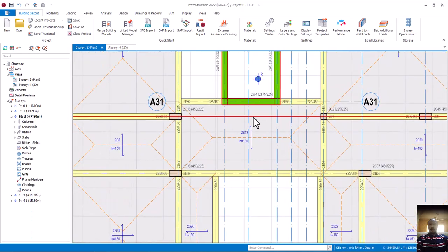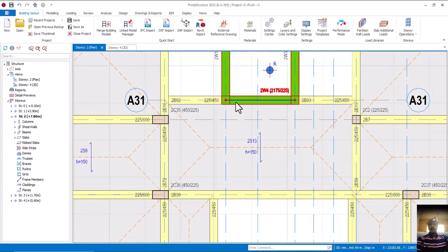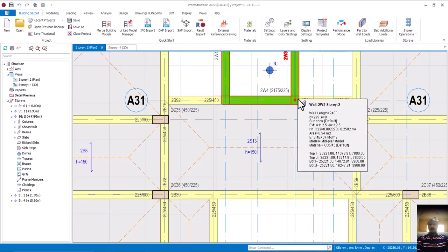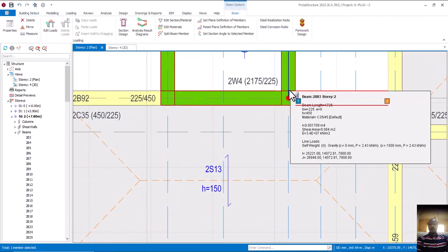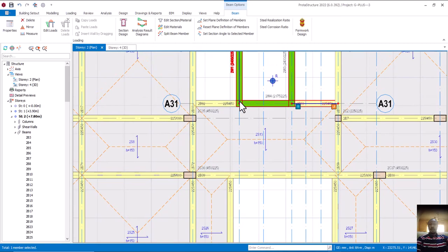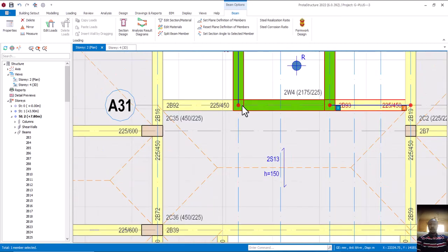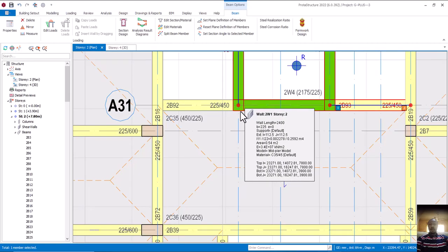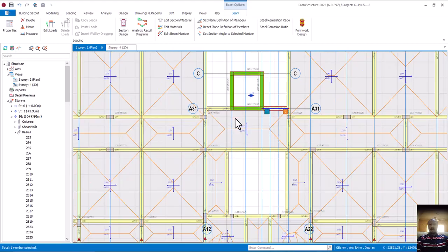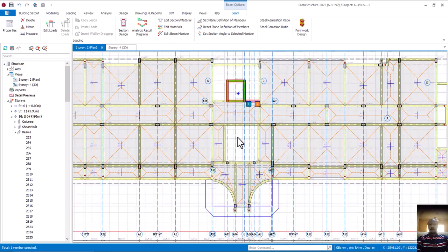Let's go back. Okay. Oh, last time we were supposed to hinge this place. Can you see? We're supposed to hinge this part that is resting on the shear wall. This particular part needs to be hinged, because it's not meant to carry moment. Is that okay? Around this place. If you do not release it, it can really cause a failure, since the wall is not actually sufficient to carry this particular beam. Is that okay? All right, so that is that.